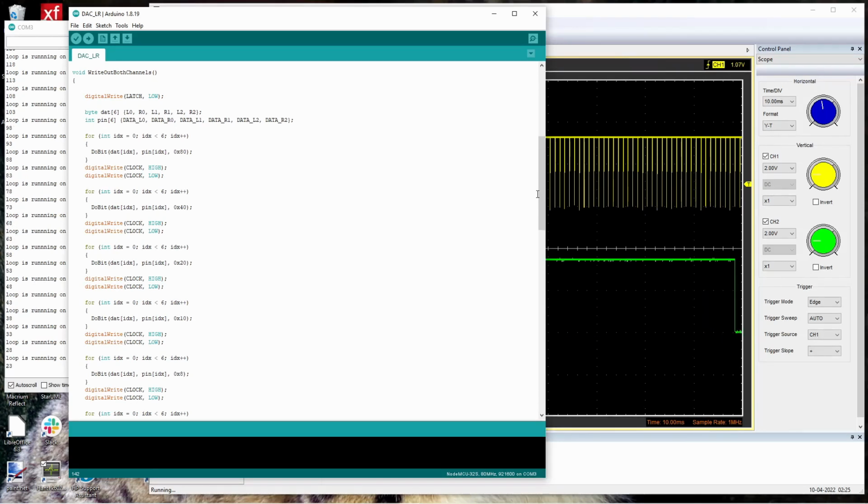And it will also make sure that it can do all, I mean, we know it can do it. The question is can it do it in less than like 10 microseconds? Because it has to be able to do all of them in less than 10 microseconds in order to work as a 96 kilohertz DAC. So I'm going to write that down. I'm going to load that on the ESP32.